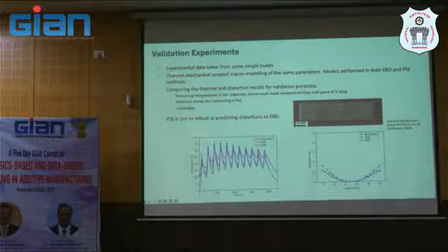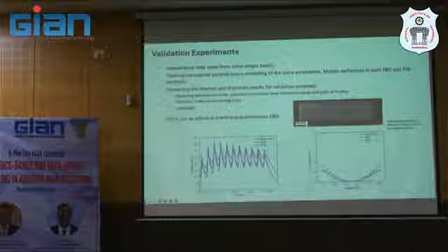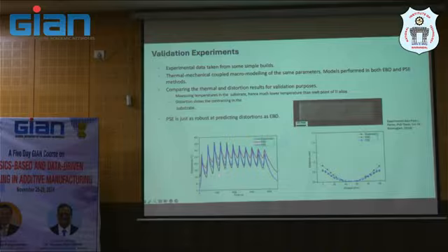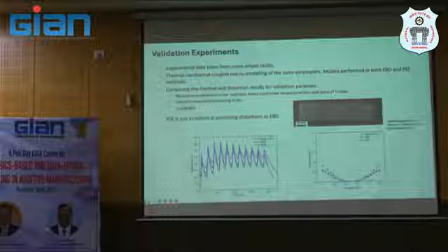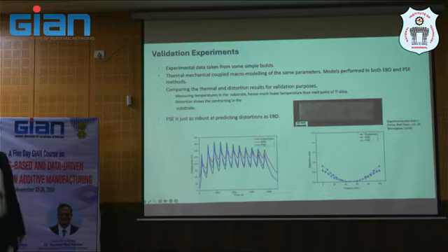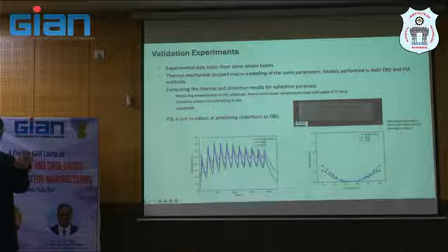So you will see that the property switching function predicted temperature at the base, using thermocouple measurement, very close to the experimental measurement here. You will see the thermal cycle start to increase and then decrease like normal. But again, it has to be noted that this is at the substrate, not in the melt pool.